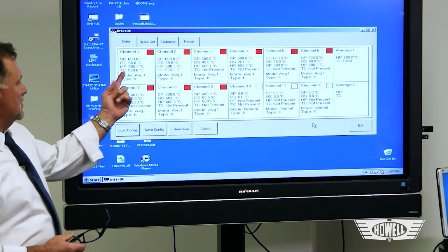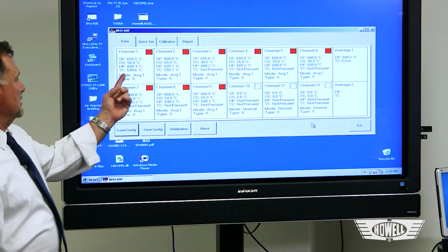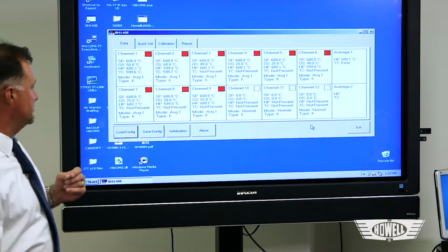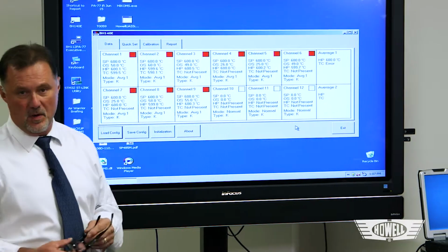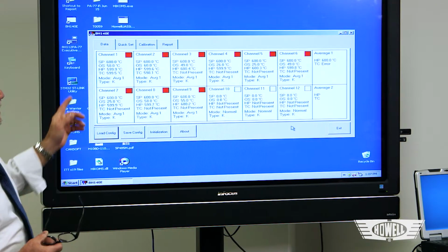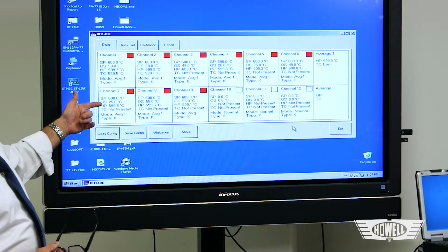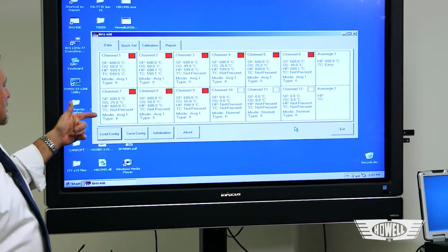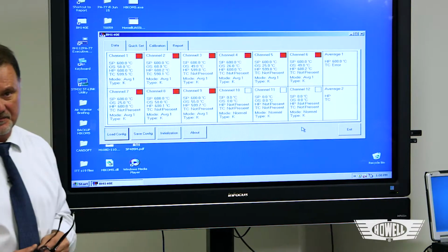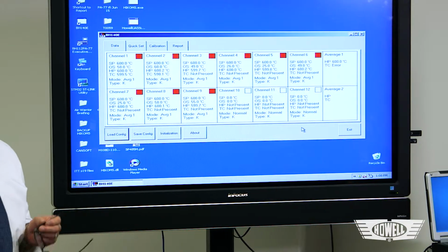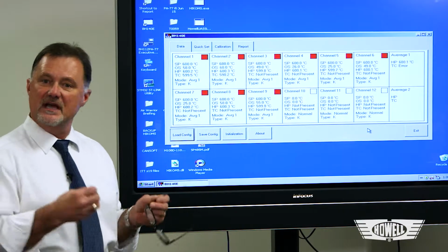What is represented here is the TC output average of the 9 that normally goes to the indicator, currently at 599.6 degrees. The TC that would normally go to the temp datum currently is at 598.1, both very accurate systems. The rest of these that have the red represent the actual heater probes that we're heating. We have a small offset, as I explained earlier, but each of these heater probes are effectively sitting at 600 degrees each. So what I'm going to do is try and simulate as many seated faults as you can, and you'll see the actual effect.